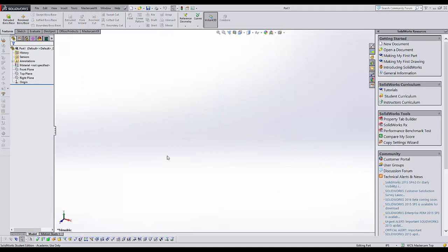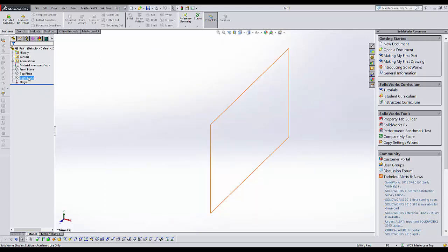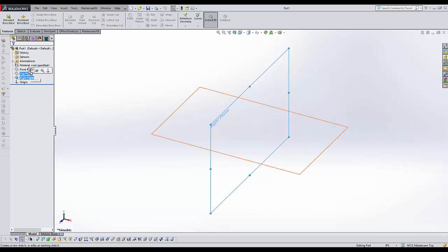Just like the orientation of the handle and the end cap, the side also falls on that same plane. So I'm going to design intent to keep it the same. I'll start there and create a sketch. Now we've been doing this: we choose our plane, then sketch. Let's try it a different way.